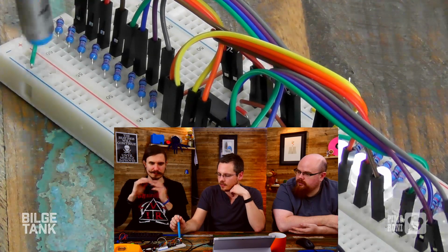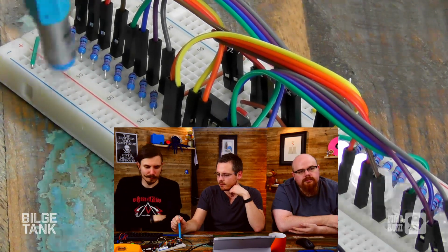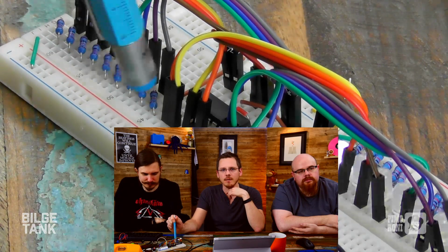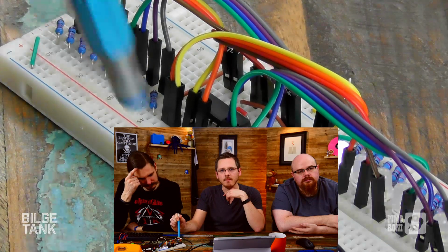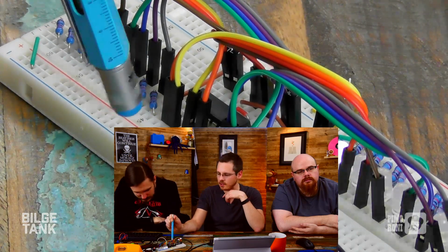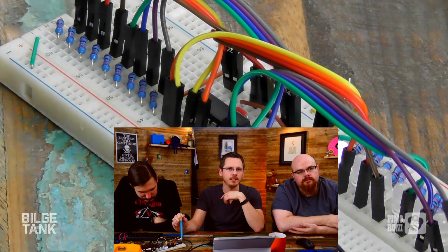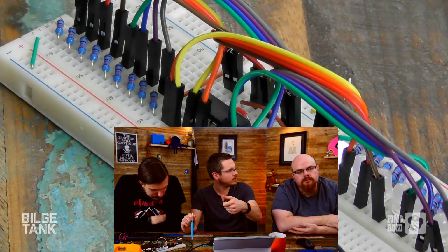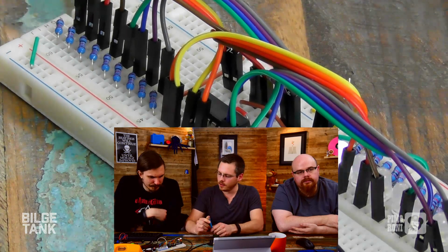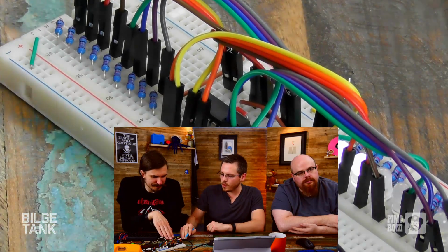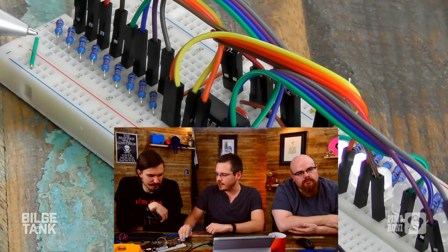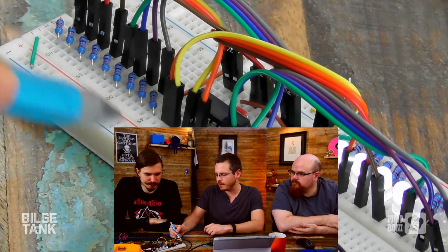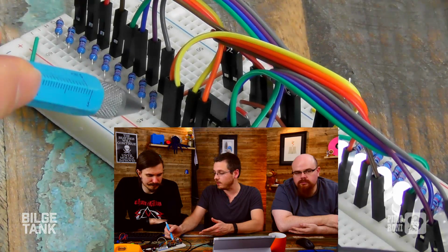What we've got here is an array of resistors. This is basically a massive potential divider, and we just tap off at each point. There are 9 resistors in here, and that's because I don't want a tap-off point at either end, because you're not going to go over 5 volts on a 5-volt system. You're only ever going to reach it. So they're all the same value then? They're all 1K, which makes this a linear ADC, because if we took the multimeter now and measured across, if we imagine that was 10 volts across the whole set.